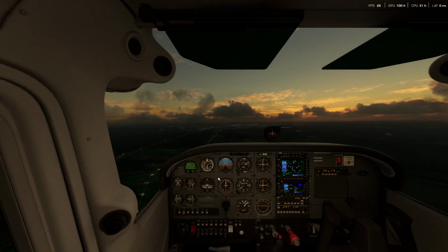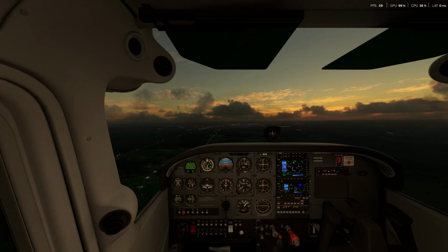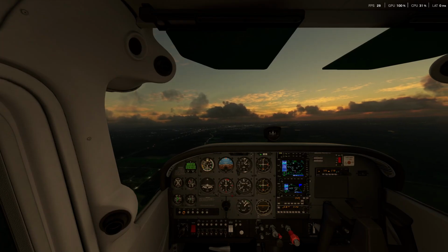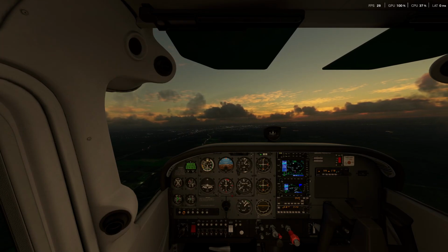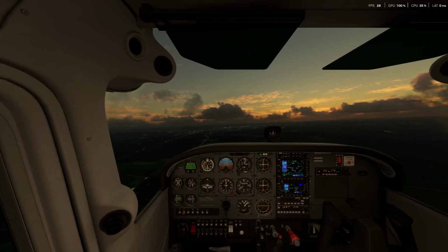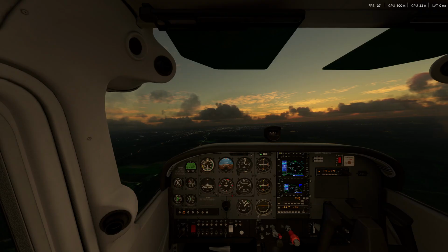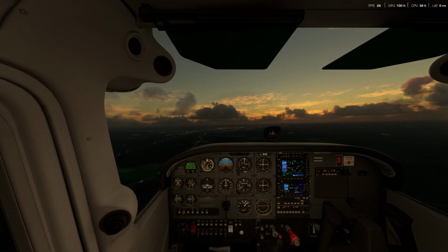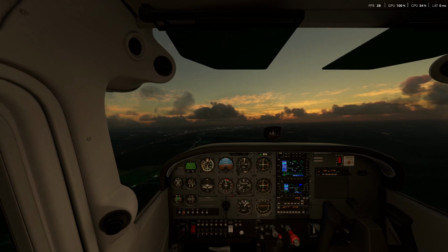So we'll go ahead and do the GUMPS check there. The ATIS and the plans are already received. Check the altimeter, 30.20 is set, radios are set. The first brief I already did. And the lights, again, for all the training flights: the nav lights, landing lights, strobe lights, and